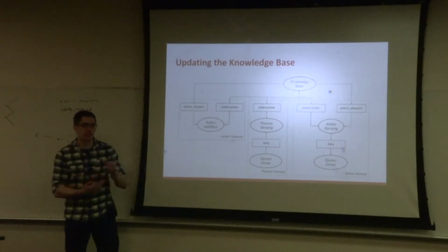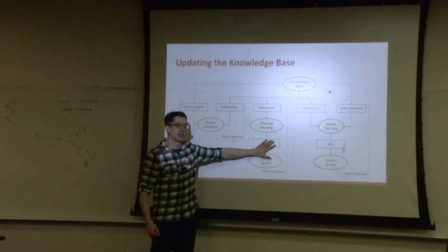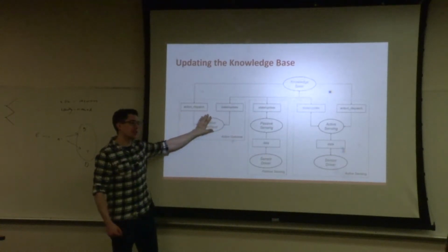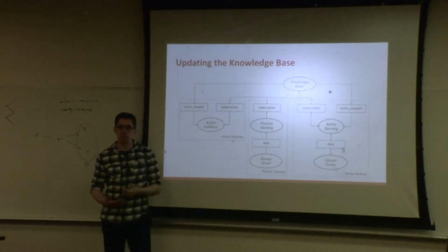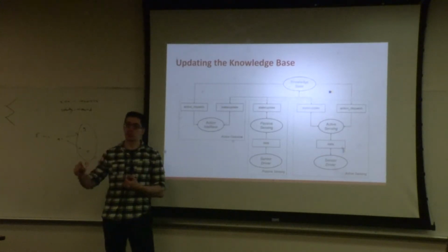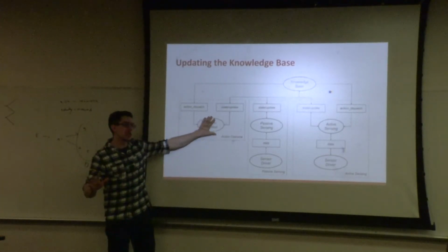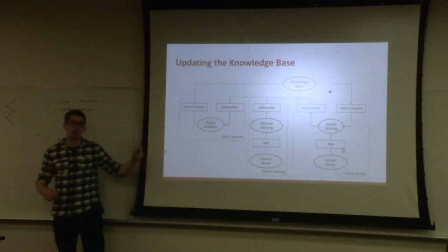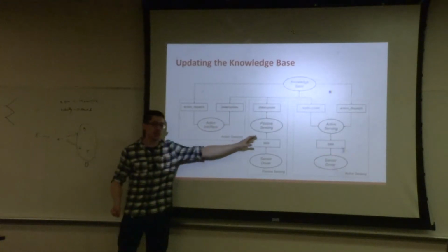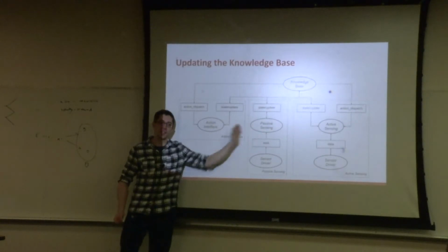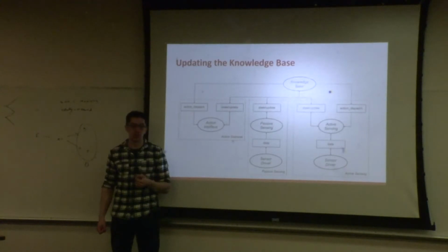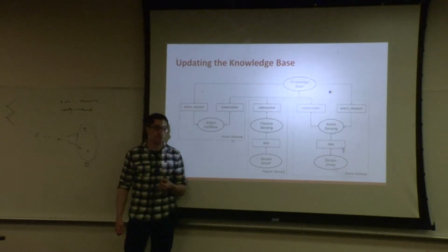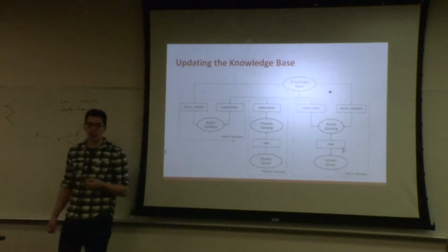Yeah, I would say that if you have passive sensing of something, you probably shouldn't use dead reckoning on it. So like if we already have a sensor that's publishing at 10 hertz and telling us whether or not the button has been pushed, and we perform the action, push the button, the action interface shouldn't update the knowledge base saying the button's been pushed now. That's the job of the sensor, because we trust it more than this one. And so in terms of determining whether the action is complete, you're relying on the dispatcher to see that change. Yep. In that case.